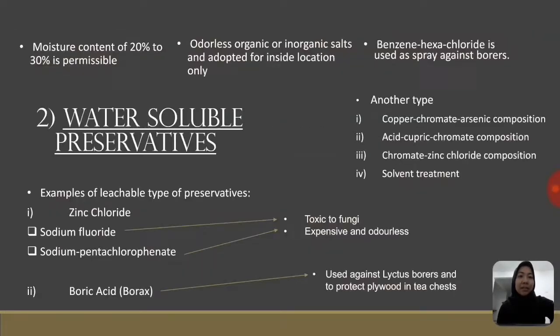The second method is water-soluble preservatives. For water-soluble preservatives, a moisture content of 20% to 30% is permissible. They are odorless organic or inorganic salts and adapted for inside locations only. And the examples of leachable types of preservatives.